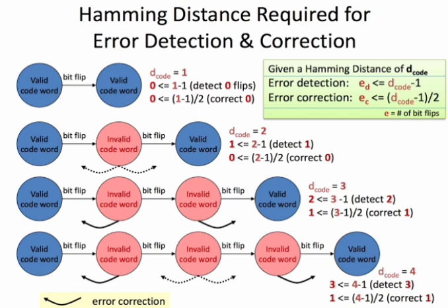G bar is not unique. That is, a code may have more than one generator. The generator matrix G bar is said to be systematic when it is in the form G bar equal to [I_k : P bar]. That is, G bar is said to be systematic when it has a rank equal to k. Every code need not have a systematic G bar.